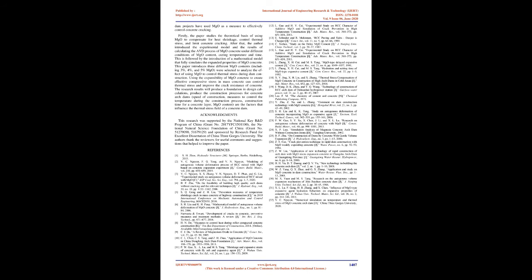Conclusion. Seeking solutions to overcome traditional temperature control measures and improve the thermal stress control capabilities of concrete dams has become a hot topic in recent years. Most of these traditional methods have a certain effect on controlling temperature and preventing concrete cracking, but it cannot be denied that these measures also extend the construction time and bring expensive construction costs. This prompted engineers to look for new construction measures to better control the temperature and thermal stress of the concrete dam. In recent years, the method of preventing cracks in dam body by adding MgO to concrete has attracted more and more attention.